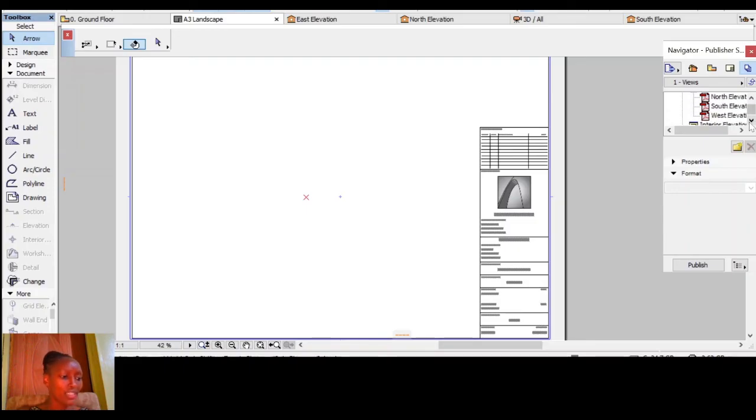The publisher set map is a tree structure in which you define sets of views for various output purposes. If you want to print, you'll be able to save those different layouts from the publisher set. You go to printing, if you want to print, to plot, to save to a local hard disk, you want to upload to the internet or the intranet, that is where you'll be able to do all that stuff in the publisher set.